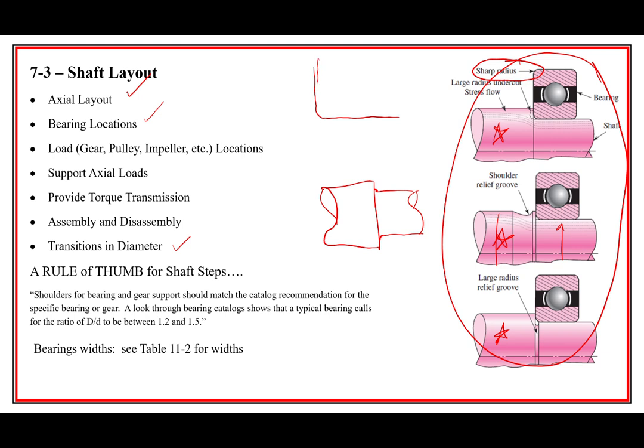The thing that's laying up against it needs to have a bigger one, so as not to run into it. Like if you had too big of a fillet right here on our part, now here is the part I was trying to draw, that makes sense right there. So the one I just drew, this is the bearing part right here. Its fillet is smaller than the shaft's. Here's the shaft right there, and these will interfere with each other. Okay, so that's the idea.